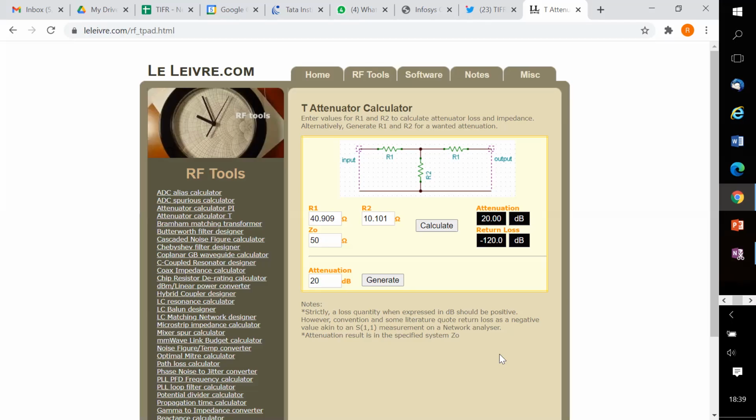If the attenuation is very high, which means very little power is actually coming out on this port, then if the boundary condition here was a short circuit, a load, or an open circuit, consider the amount of power that will come back in case it's not 50 ohms.